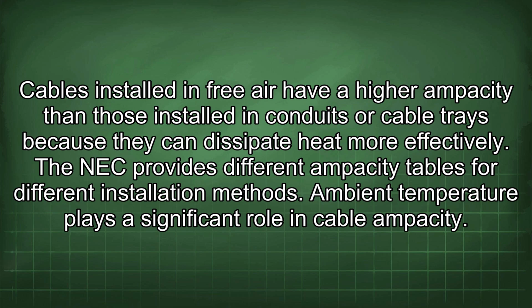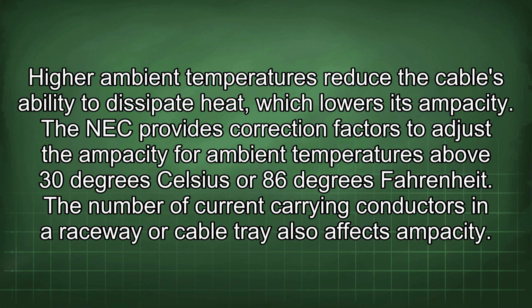Ambient temperature plays a significant role in cable ampacity. Higher ambient temperatures reduce the cable's ability to dissipate heat, which lowers its ampacity. The NEC provides correction factors to adjust the ampacity for ambient temperatures above 30 degrees Celsius or 86 degrees Fahrenheit.